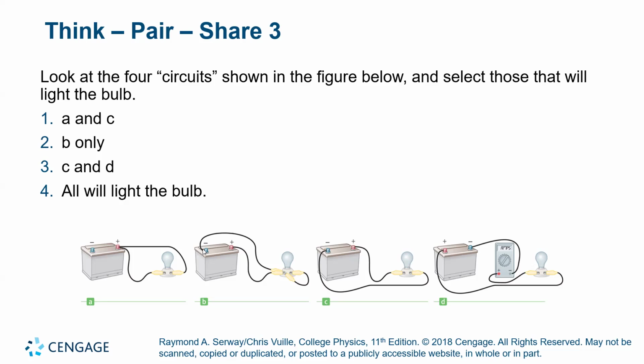Now this allows the current to flow, but it doesn't actually need to go through the light bulb if these two leads here, I'm going to draw, make sure you're looking at the same thing. If these two leads are connected to each other, like with a wire, there is no path that has to go through the light bulb. It simply continues its path, and this will basically burn out the battery. Could cause a very dangerous situation, in fact.